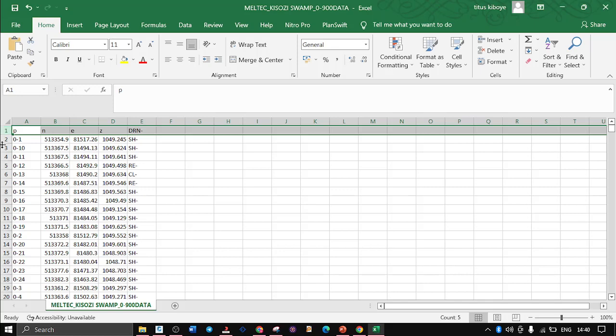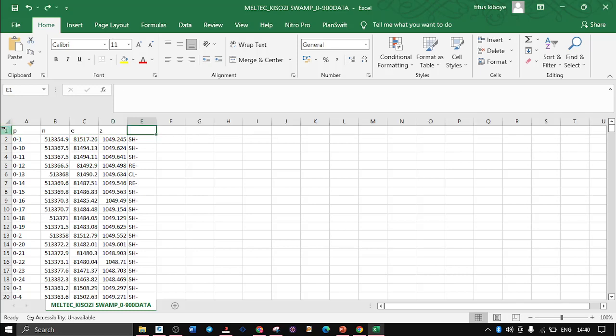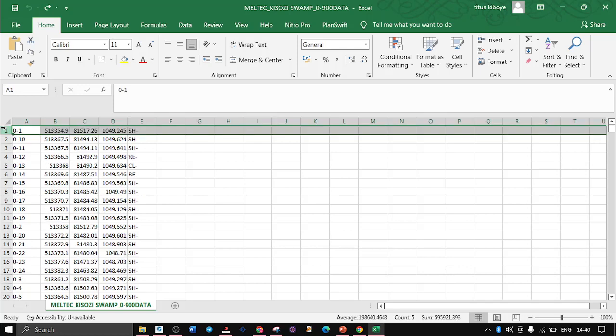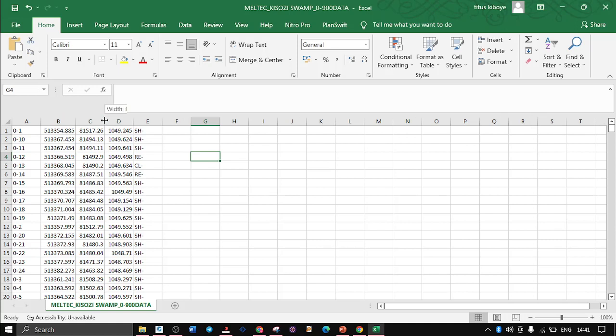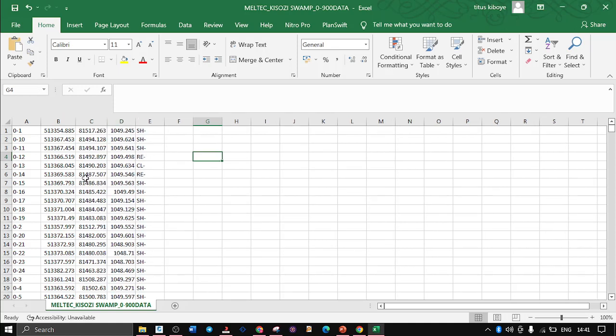Have you written those two formats? Yes, I've written. Now, I don't know in which file format this data was recorded. Is it PNEZD or PENZD? Which file format was this picked? Of course, now the higher ones are the what? The eastings are always higher than northings. So that's what they told you. The surveyor, the one who picked, told me that.